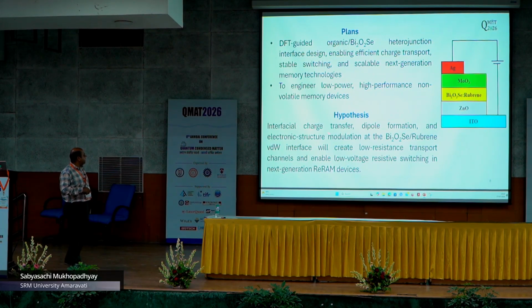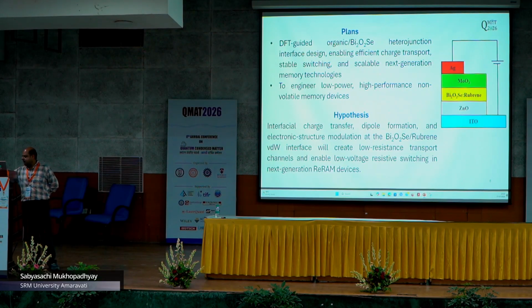The hypothesis we are taking is that there is an interfacial charge transfer, there will be dipole formation at the organic-inorganic interfaces, and then electronic structure modulation at those interfaces, which will create low resistance transport channels when we apply the voltage, and vice versa will happen. And we can use it as a low power memory device application.